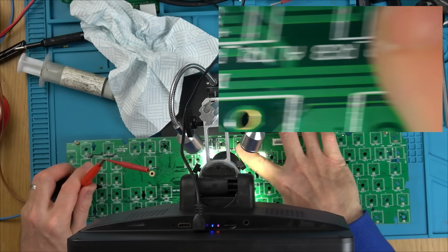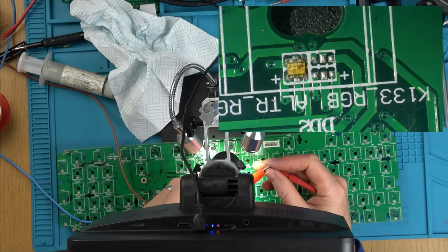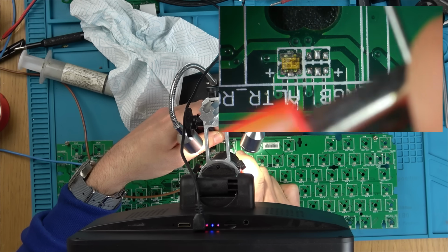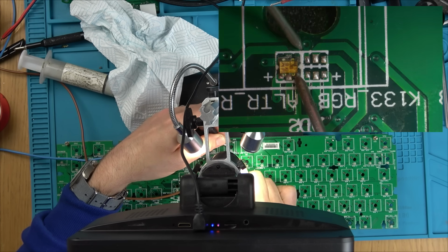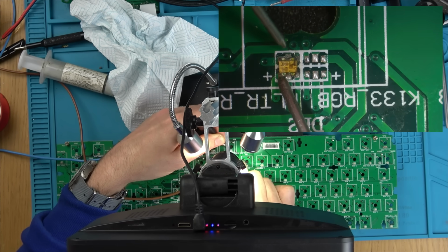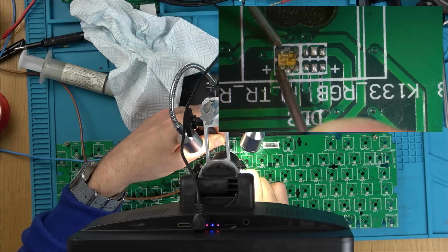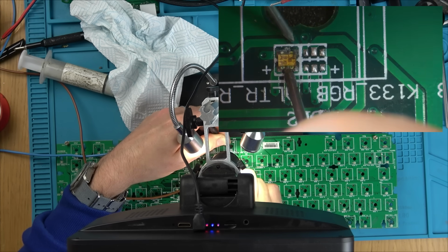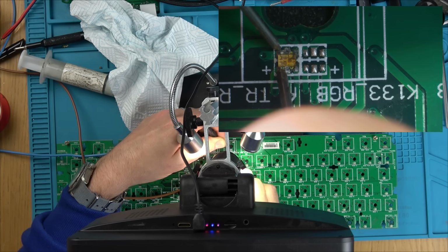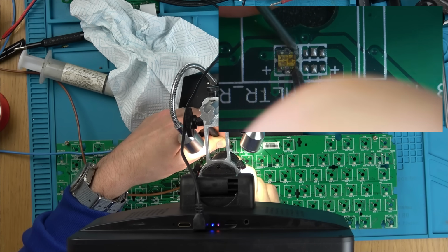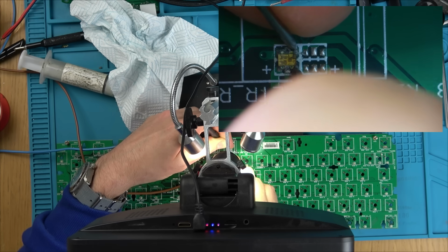Let's go down to this one. And let's see what colours this is going to do. So this is on its side. So where's plus on this one? Plus is up here. Alright, okay. So this should be red. This should be blue. Yeah. There you go. So on this one, the green's not working. The red is working. Blue's not working. And you can see they're actually discoloured. Oh, what a shame. Alright, well, we proved what the fault was.